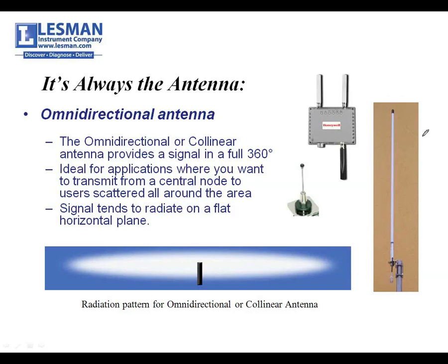This white antenna over to the right is an actual engineered, modified, what they call a high-gain antenna, and it takes the pumpkin-shaped energy and smashes it down. When it does that, it reaches out farther, so you end up with a flat but very far-reaching antenna energy range, as is shown here.